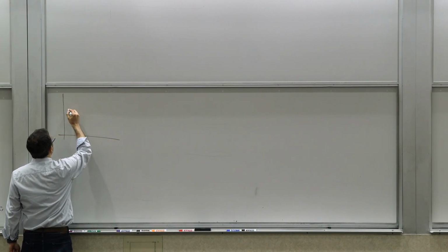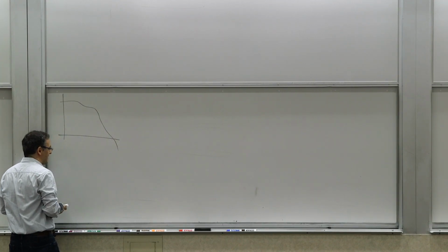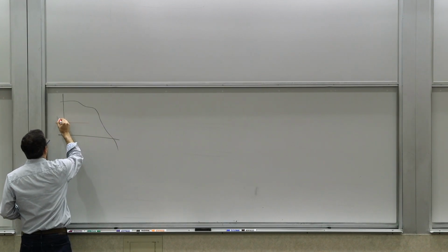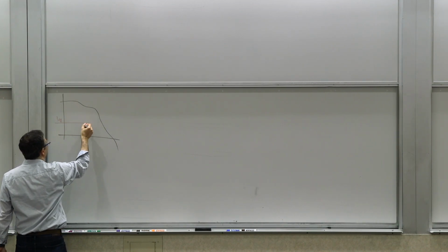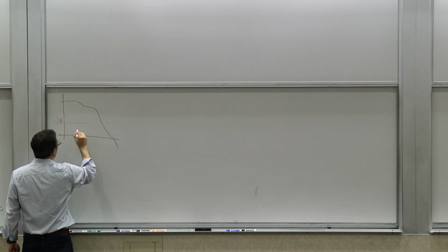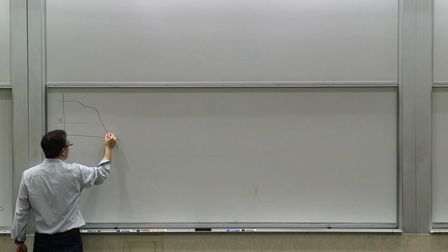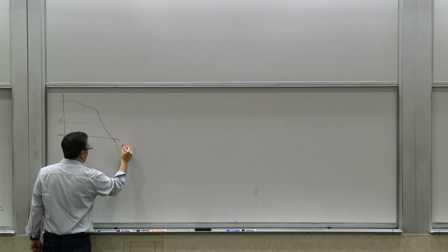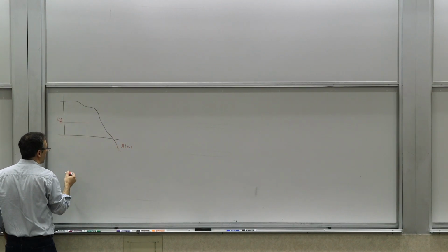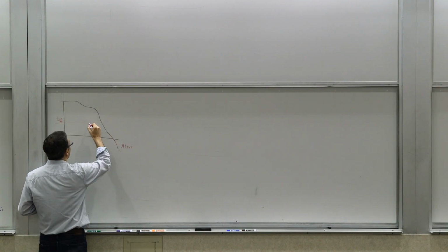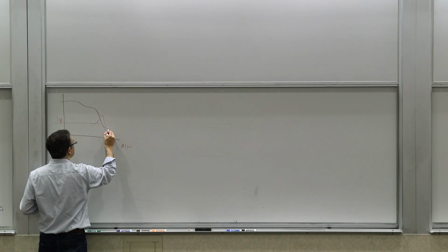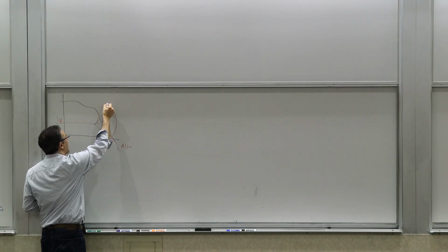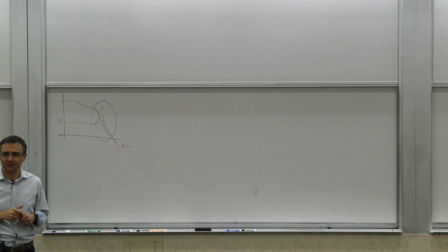You remember we said if you have an amplifier with some dynamics and then you apply some sort of feedback to it, we saw that when A times F was much larger than 1, you basically got a transfer function that looked like 1 over F. And when it was much smaller than 1, you basically followed the transfer function of A, A of j omega, and this was basically 1 over F of j omega. But in between, interesting things can happen. And now we are going to talk essentially about why and what can happen in here.